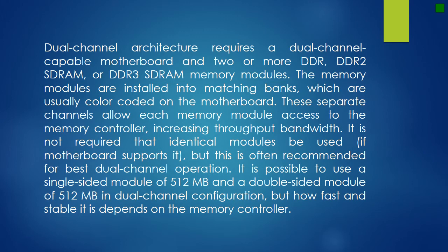If the motherboard has two pairs of differently colored DIMM sockets, then one can place a matched pair of memory modules in bank 0, but a different capacity pair of modules in bank 1, as long as they are of the same speed. Using this scheme, a pair of 1 gigabyte memory modules in bank 0 and a pair of matched 512 MB modules in bank 1 would be acceptable for dual channel operation.